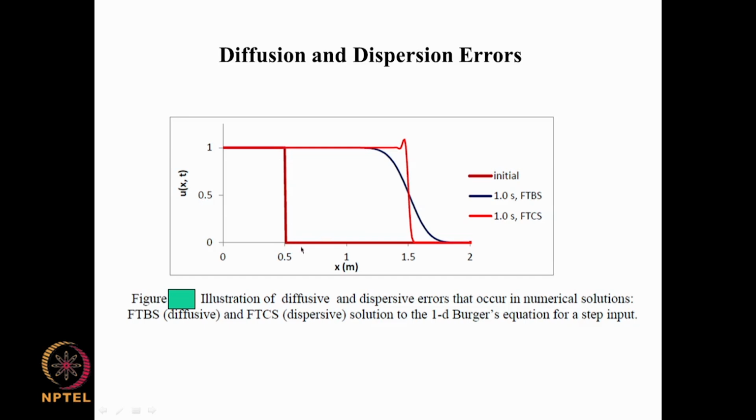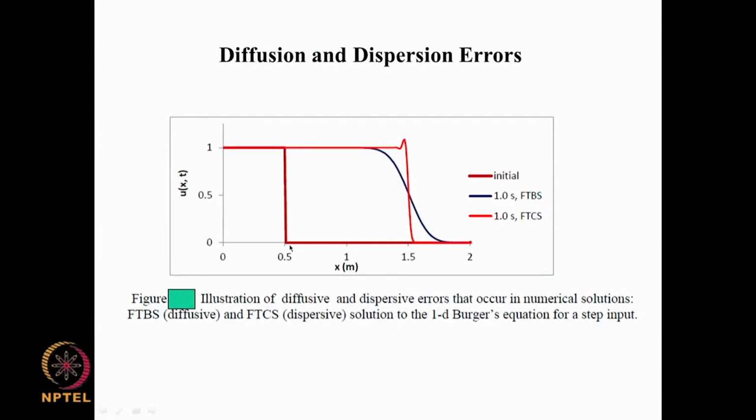this gradient well, we need to have better differencing schemes than highly diffusive FTBS scheme or dispersive FTCS schemes, and people have come up with the concept of total variation diminishing TVD schemes and ENO, essentially non-oscillatory schemes like that, to get a solution which is as close to a square pulse as possible for this type of thing.